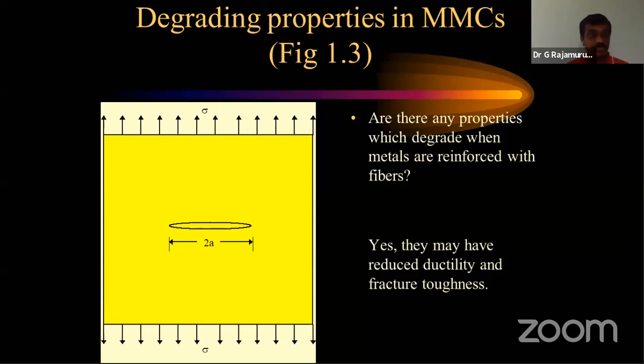But in a composite material, as I told you just now, whatever particles you add in the particular composite, the structure may be whole, but inside there won't be any bond between each and every particle. So in a composite material, fracture toughness is a challenging job, because there are two types of crack growth. I think you all know that. One is intergranular, another one is transgranular crack.